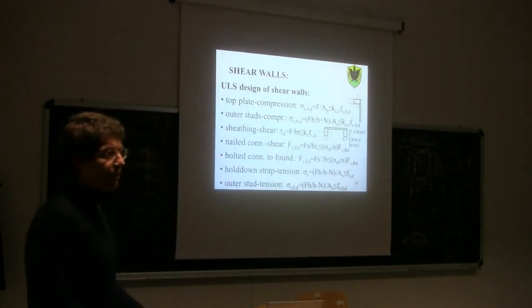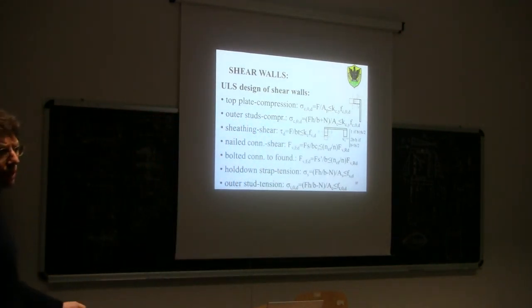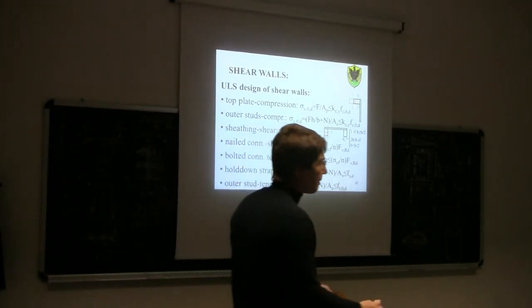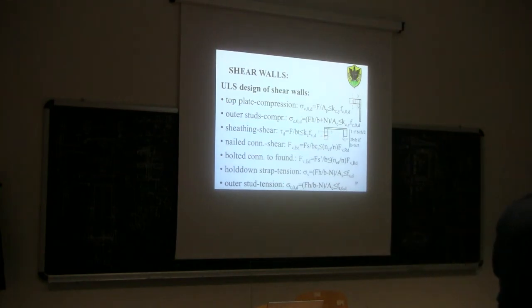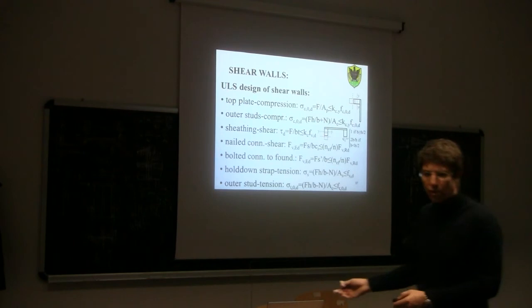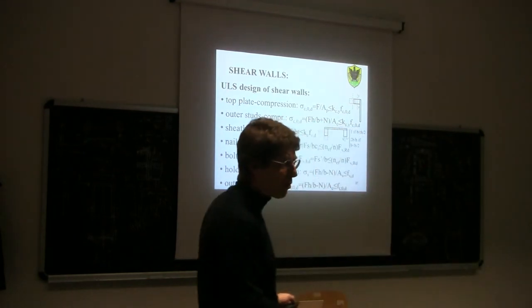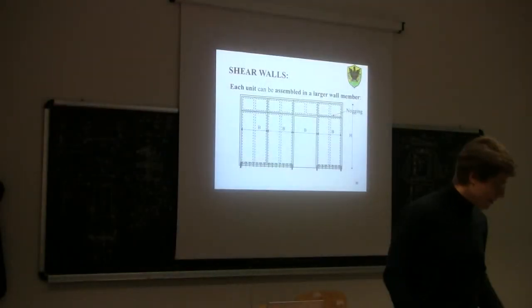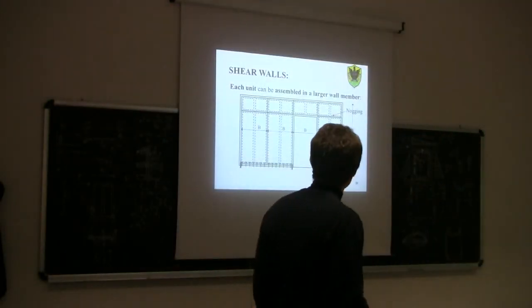So basically here we solve the problem by using the equilibrium. So all these solutions are just, if you want, very simplified solutions obtained just using equilibrium. So no compatibility, no stress-strain constitutive relationship. It's very basic, but for our problem it's more than enough. In fact, in general, those kinds of structures are always designed using this kind of approximate equation that we found before. We should make a start to try to finish for today.